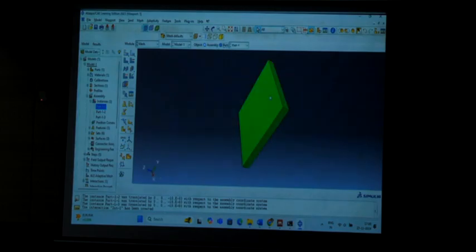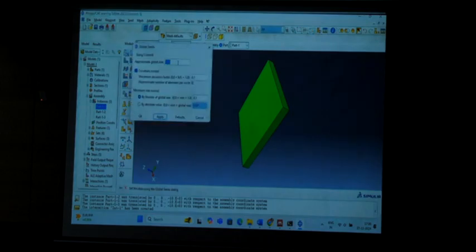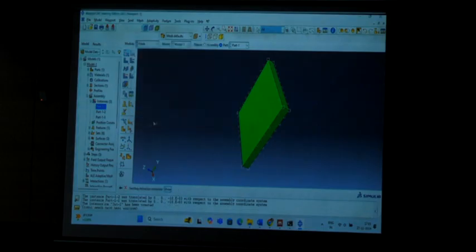It will choose the single part, same as the seed parts we have given. It will approximate the global size as 0.01 or something like that. If you go for a larger size it won't work, because if the number of nodes is greater than 1000 it won't work. So just choose the better default option, which is suggested for initial learning conditions. This is everything. If you have a licensed version you can work with a finer mesh. Just click on OK.